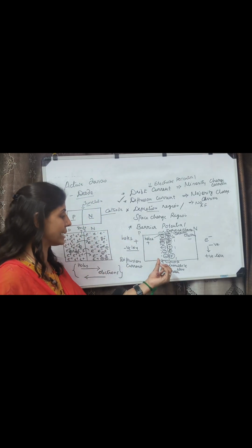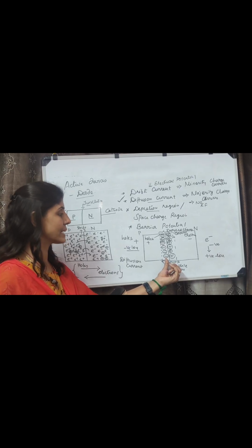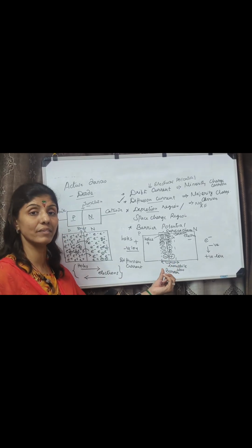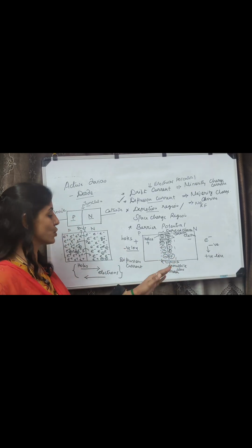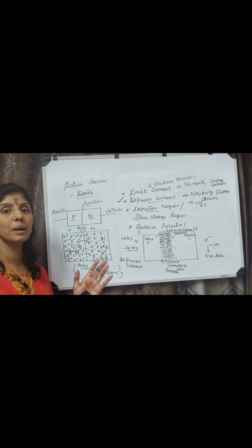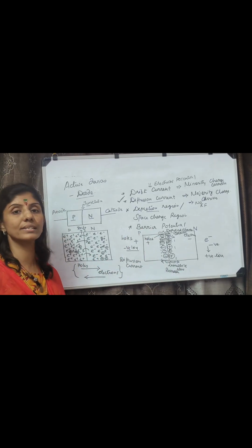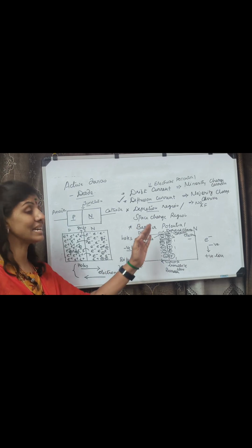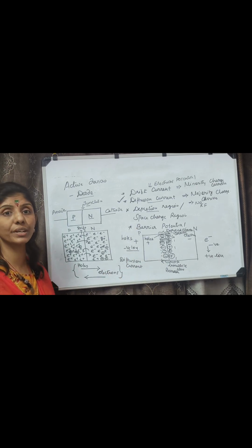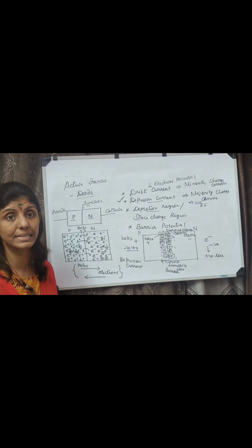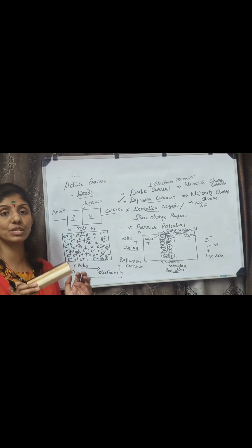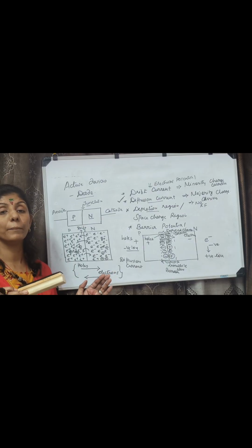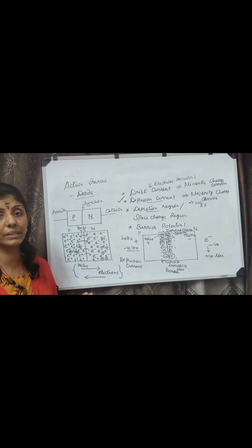Even as it is a barrier, see here, a negative ion is here as well as a positive ion here. In a way, some potential or voltage will be produced near the junction. That's why this potential is termed the barrier potential and this region is the barrier region. These all happen in the PN junction diode once it is fabricated itself, without the application of any electric field. I am not applying any electric field, I am just fabricating, making my P region combined with the N region.